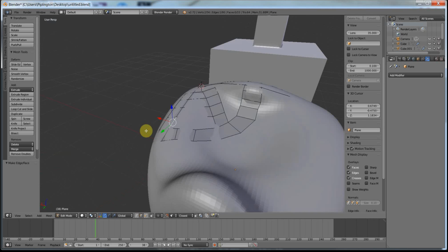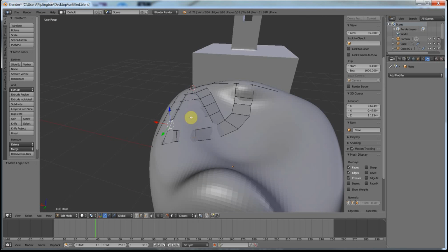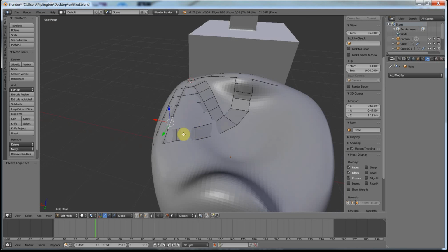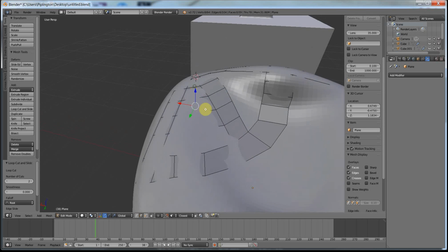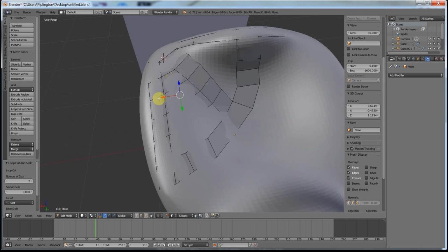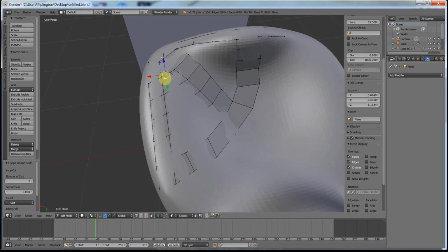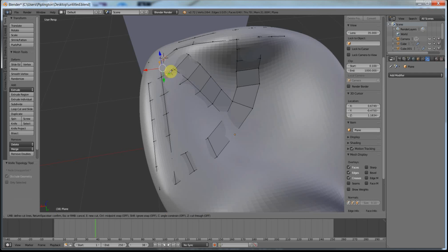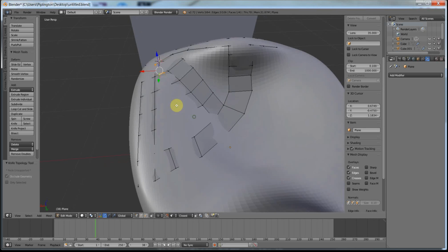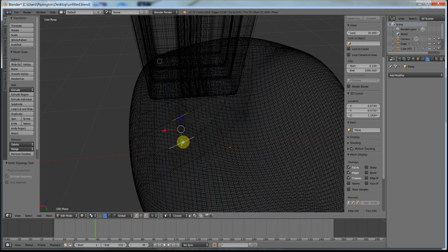And now I haven't got enough information because I've got 2 edge loops here. So I'm going to put in 2 edge loops there, creating a shape that I can fix by cutting here with K. And then select these and fill it in.